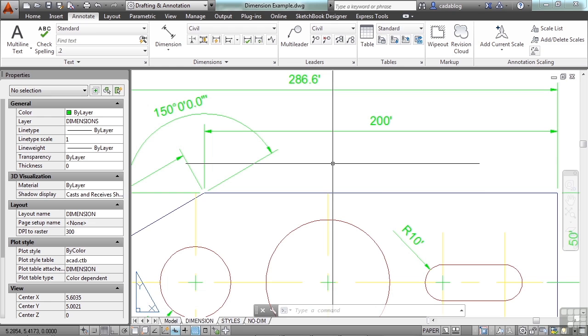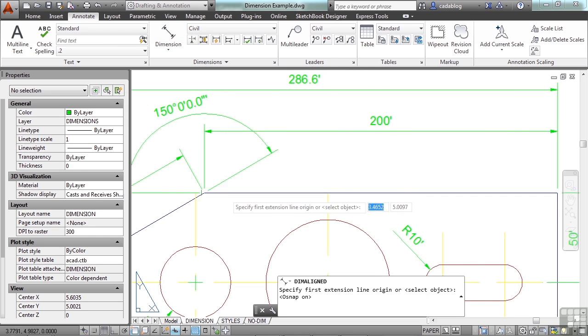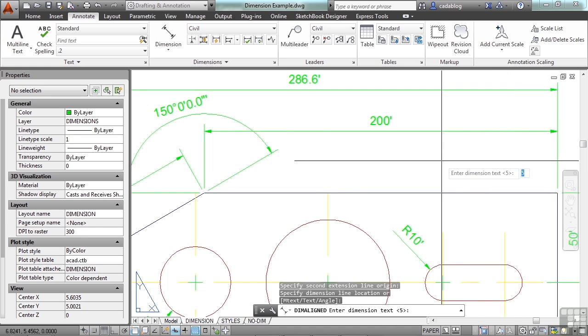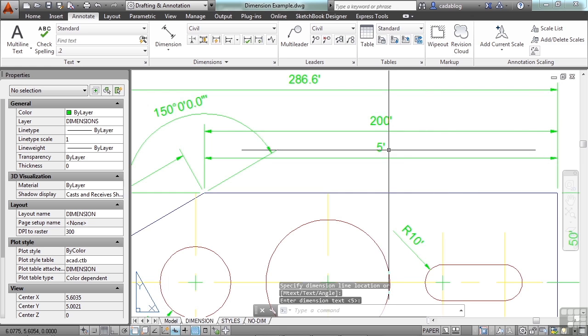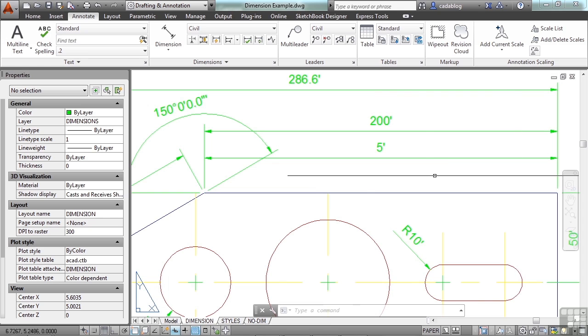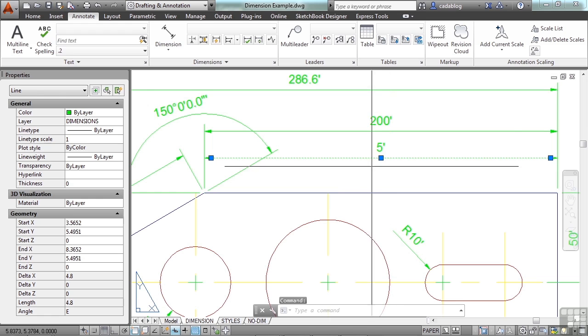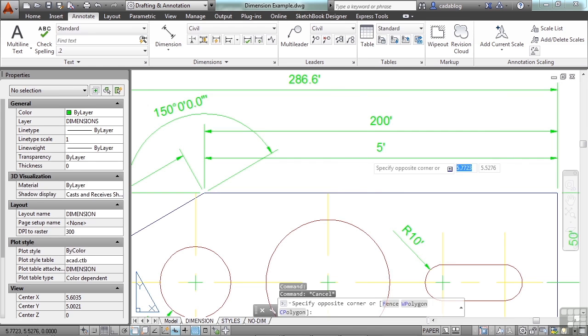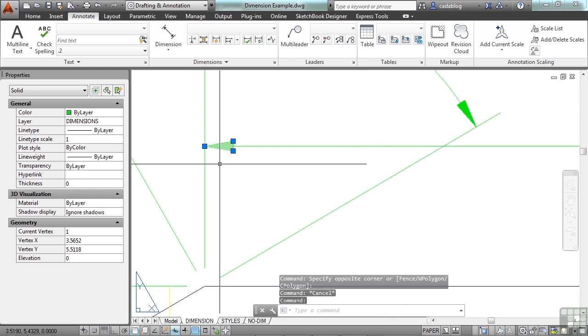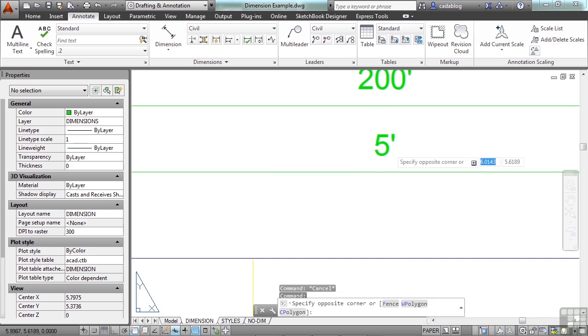If you have your dimension associate setting set to 0 and you create dimensions, they'll look like your style and they'll just draw everything else the way it needs to be. Except you see here, it's not scaling it properly. It's just drawing it to the scale in paper space. So you'll have to enter in the text the way you need it to. And it's not a dimension style. It's just a line. Several lines. The arrowhead is just a solid shape, and your text is just text.